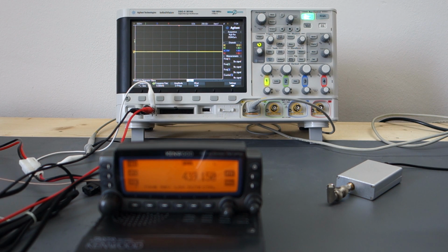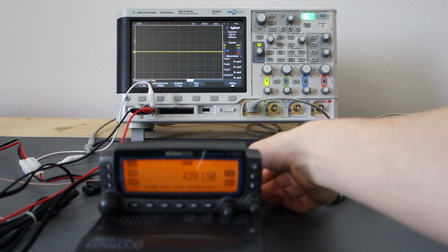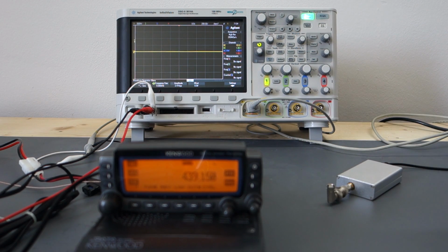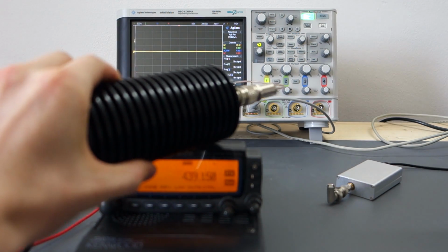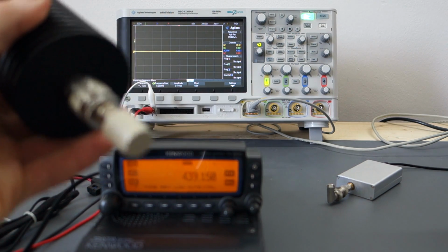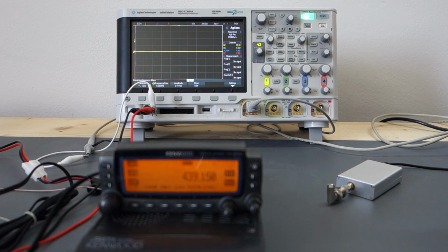I'll demonstrate that real quick too. Now it's transmitting here at maybe 5 watts or so. I could make this neater, but I tried and I broke the connector, so anyway, that's what it is. The radio itself is just connected here to a dummy load. Let me show you that too. This is the dummy load here. Actually, it's not a dummy load, it's a power attenuator that I even terminated in 50 ohms, but that doesn't really matter. So that's the transmitter side of things.